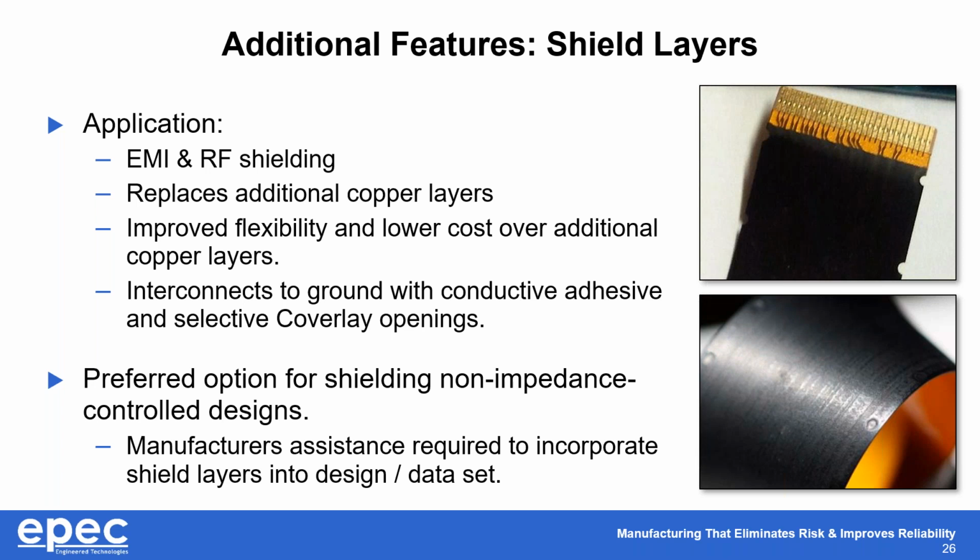The shield layers are laminated on top of the coverlay, so there's no additional drilling processes, no additional plating processes. The shield material has an electrically conductive adhesive, which through selective openings in the coverlay that expose ground lines in the circuitry, the shields laminate on and electrically interconnect to the ground through the conductive adhesive. By far, it's the preferred option for shielding designs that are not impedance controlled.